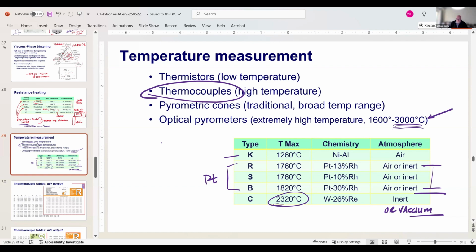And then you have to be able to see into your furnace. If you can't see into your furnace, you don't get an accurate measurement. Both of these, thermocouples and optical pyrometers, are susceptible to contamination or being obscured. Blockage, we'll call it.